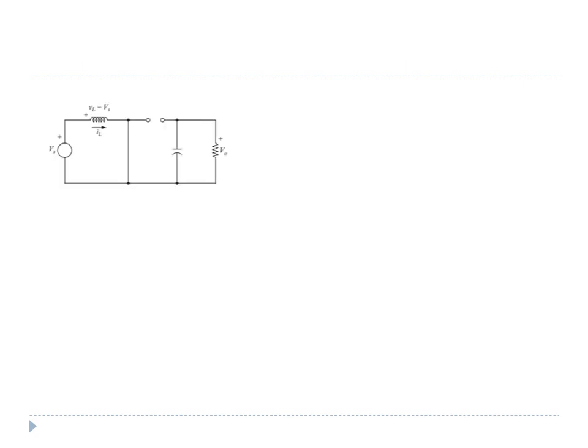The detailed working of the circuit is presented here. When the chopper is on, the supply voltage comes in series with the inductor. The diode is reverse biased, so the supply voltage is disconnected from the load.